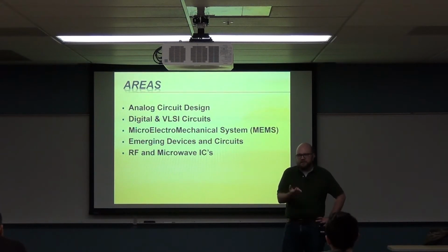So there's a weird problem, which is that there's a gain bandwidth constant for the little black box that's the op amp. Somebody will say something like it is a 100 megahertz gain bandwidth. So the bigger I make the gain in that amplifier, the lower the frequency it can put out. The lower the gain, the higher the frequency it can put out. And if I want that little black box to have a higher gain bandwidth constant, I need to do a lot more work.